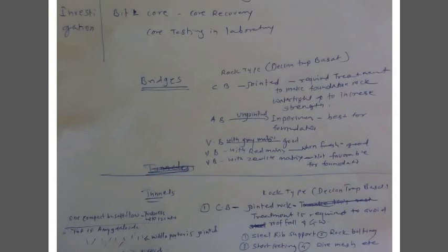Tunneling was without any problem. But towards the Mumbai portal, the tunnel passes through the middle portion of the compact basalt. The tunneling was troublesome, and treatment and support were provided there. So this is the best example of tunneling in compact basalt and amygdaloidal basalt.